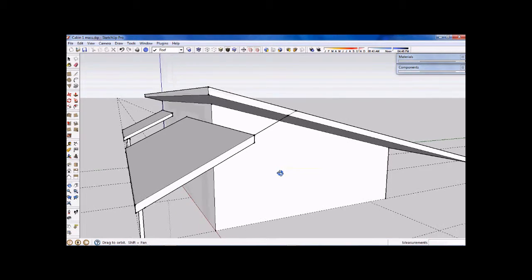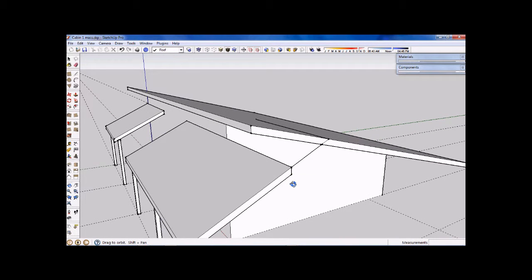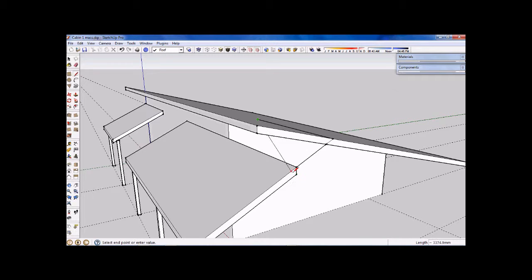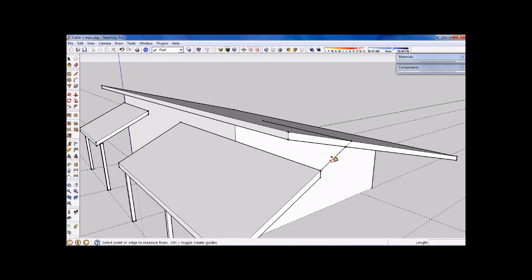So we should be able to then, I think, if I've done everything right, I've got to remember, of course, that this roof is 10 millimeters away from the other roof, and in fact I want to do the same thing again, but I'll close this up to start with. So I think to do that I might create a construction line. So I'll grab my tape measure, and I'll click my tape measure along this edge that we just created, and I'm going to pull that back until it's in line with that end point up there. And it's actually reading 3150, which is what we'd expect.